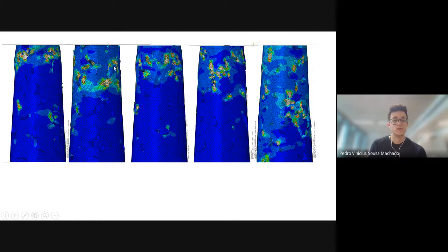Also here, if we look at this, sometimes we almost see the outline of a carbide just from the deformation field around this model. So this is telling us that although we didn't specify any interface, the simulations are telling us that around carbides, the geometry is critical. There are a lot of sharp corners, and this is where cracks begin.